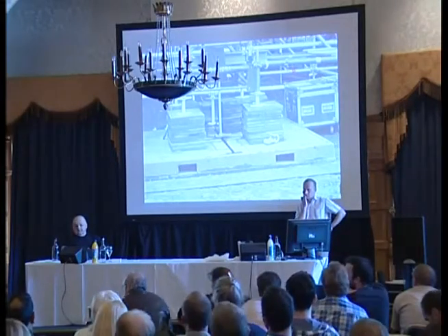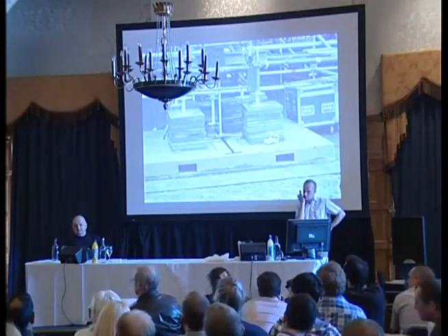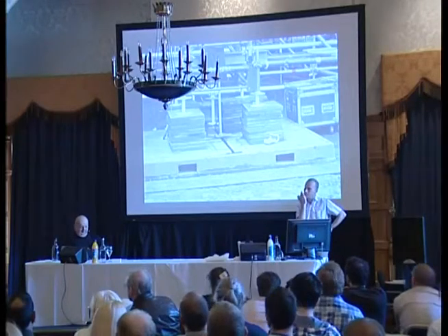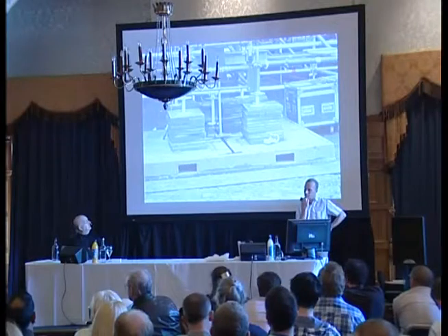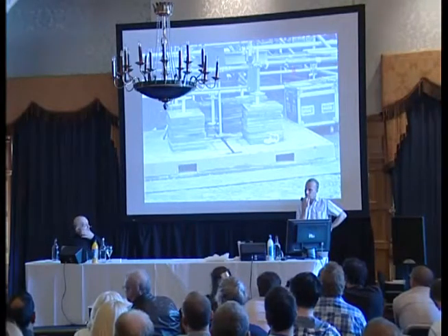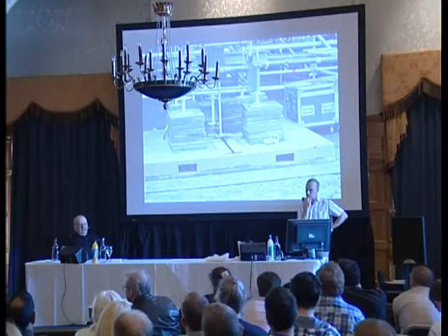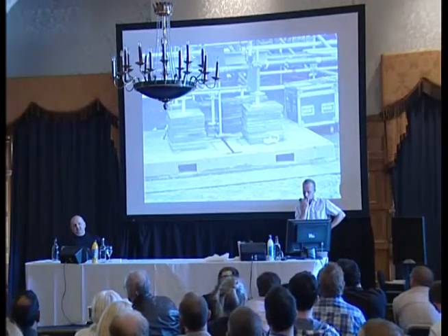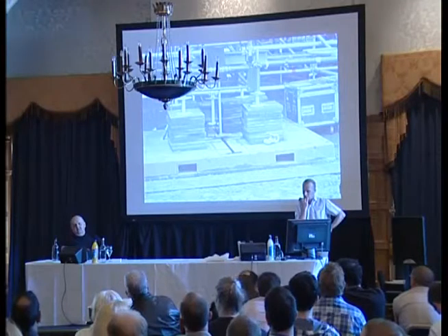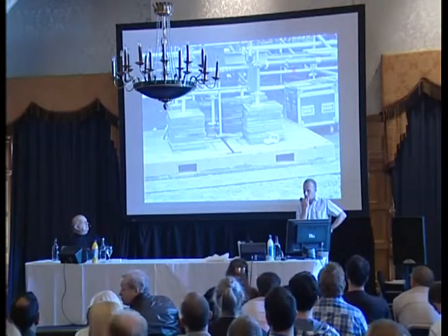But a good sign-off sheet should have scope where you can write a deviation, and you want to have the deviation checked through with a phone call going back to the drawing office. So you could say that it's been followed through and they were safe to do that, so then they can sign off. But you don't sign off as per drawing with a deviation, you declare that as a deviation, wouldn't you? But you try and go back and draw that on a CAD.